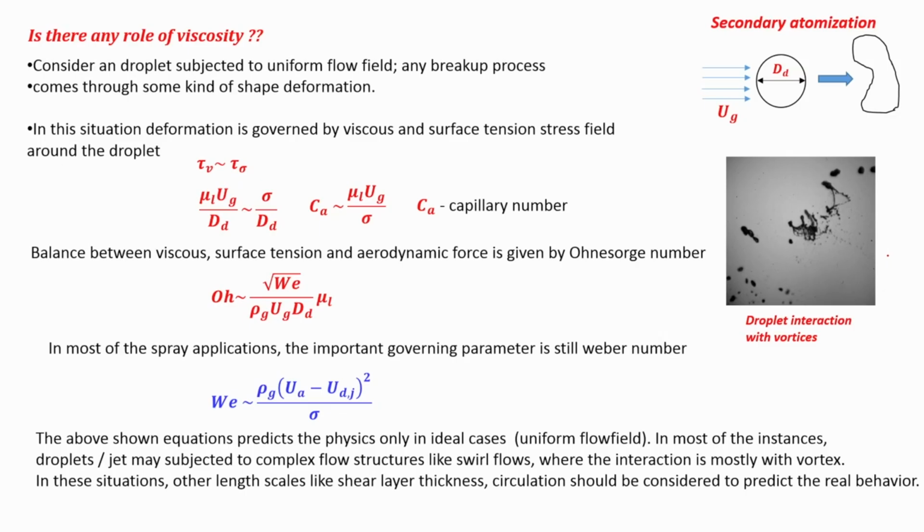Now, you know that the breakup process is not an instantaneous process. You have a droplet which is facing this gas phase flow field, that is what we covered. The droplet will first deform, it will deform more and then it will break up. It will be several stages, maybe the next step will be like this, after that it will be like this, then after that a small droplet may come out from both sides. There is a process. It is not like this immediately breaks up.